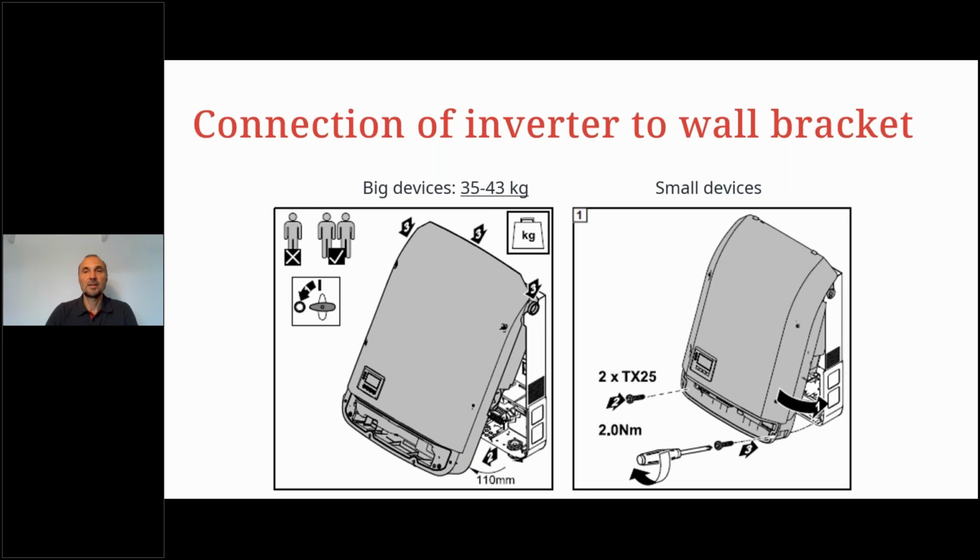Take care to use the right torques. 2 Newton meter is usually the torque you have to use on the closing of all the screws here. So 2 screws first when you have closed the inverter, and then the cover as well.